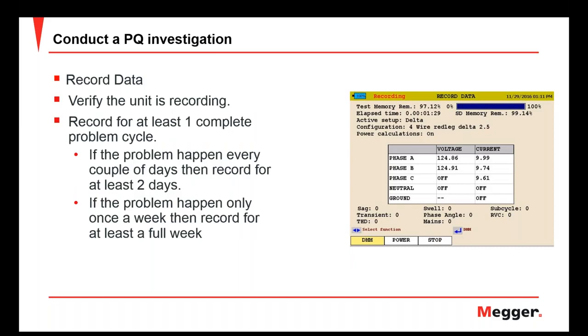And before you walk away, just make sure that the analyzer is recording. I cannot tell you how many times we've had people set them up, made sure everything was right, and then left, forgetting to actually start the recording.